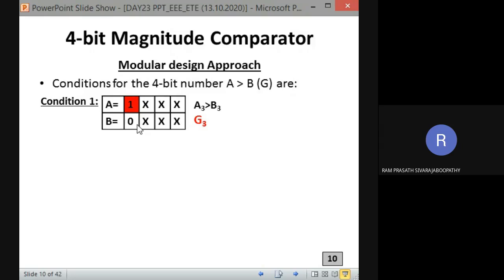See, we are having 4 magnitude comparator, 1-bit magnitude comparator. In that we are considering only the MSB now. If A3 greater than B3, which one of the output of the 1-bit magnitude comparator must be high? So 4 magnitude comparators, say for example LSB 1, 1 2 3 4. So the 4th comparator's output G3 alone can be high. Is it clear now?